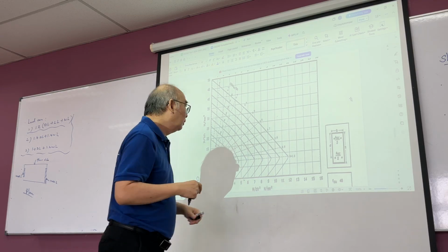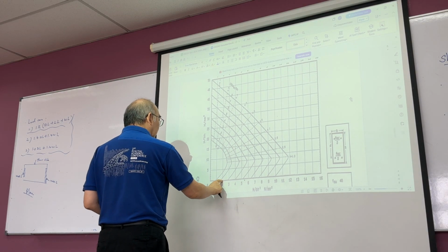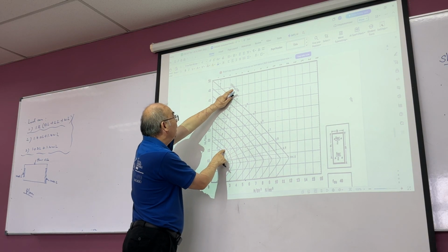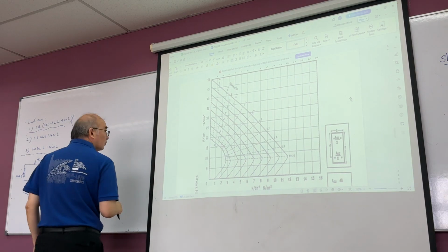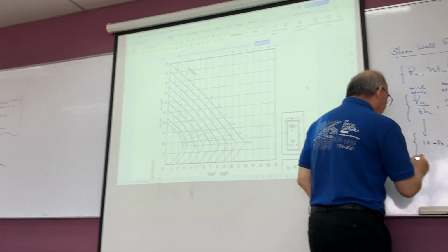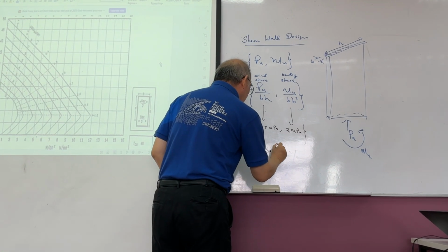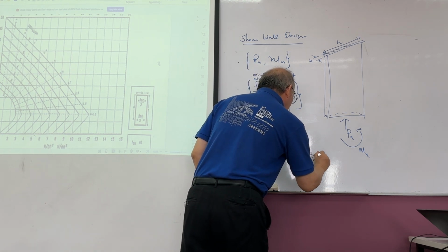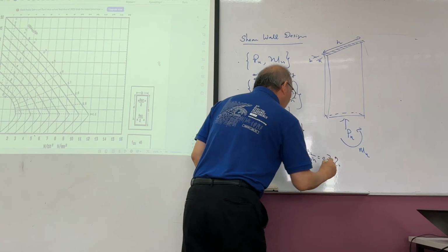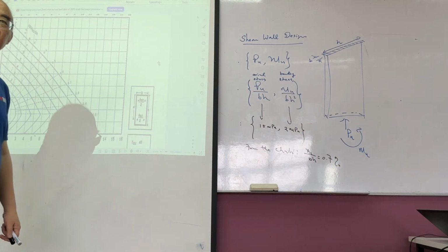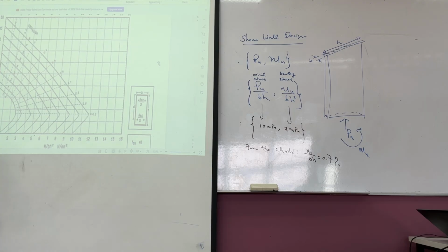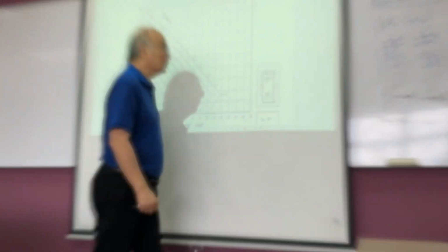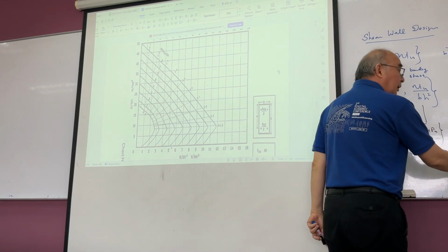0.7, right? So here 2, 15 is 0.7. So 0.7 of what is AS over BH. So from the charts we come to AS over BH is equal to 0.7% of steel. Understand? That means this is 0.7, that means 0.7%. Okay.